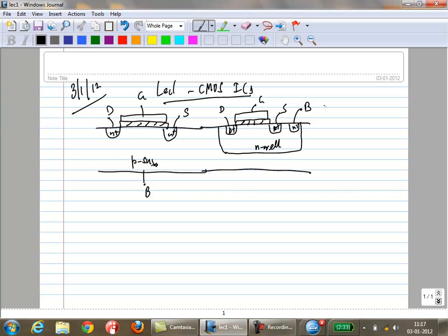Okay, so back to the topic. Now you have the NMOS and the PMOS. What other kinds of circuits do you need? You need to make connections, right? So you need metal lines to connect the drain, gate, source, and bulk connections. So let's say this is the poly. You also have multiple metal layers. Typically these CMOS ICs have multiple layers.